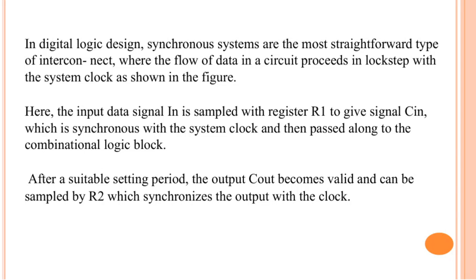In digital logic design, synchronous systems are the simplest and most common type of interconnect. The key idea is that data flows through the circuit in perfect coordination with the system clock. Here, you can see that the input data signal, labeled in, is first captured by register R1. This step is crucial because it converts the input into a signal, CIN, that is synchronized with the clock.